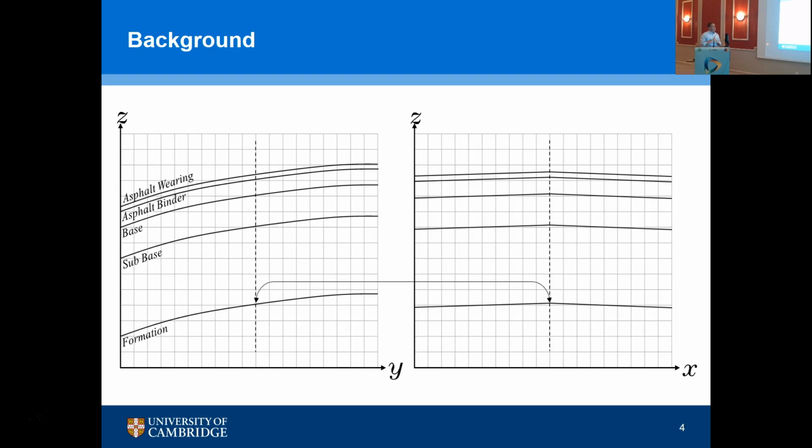If I'm wanting to look on a per voxel basis to determine the presence of a design surface, I want a consistent framework. If I look at, let's say, the subbase on the far left, that surface is intersecting the voxel in the bottom half. If I look in the upper right, it's intersecting the voxel in the top half there. So I don't have a consistent framework for attributing points to that design surface, and that's going to cause some error in and of itself.